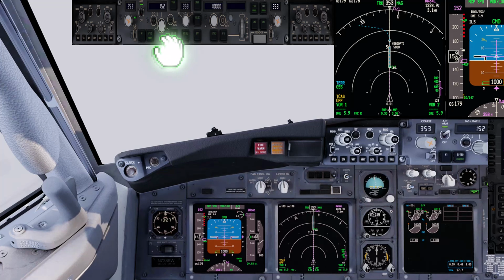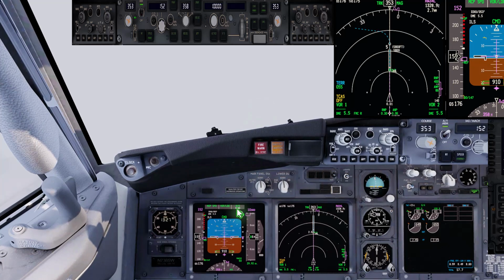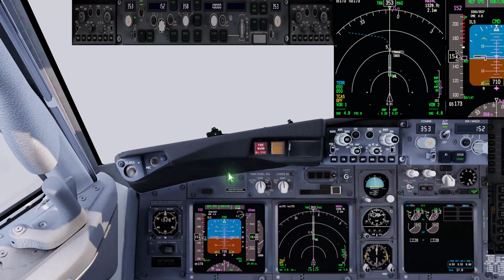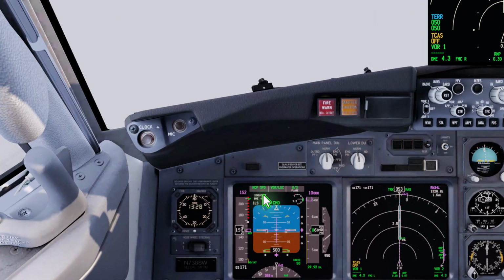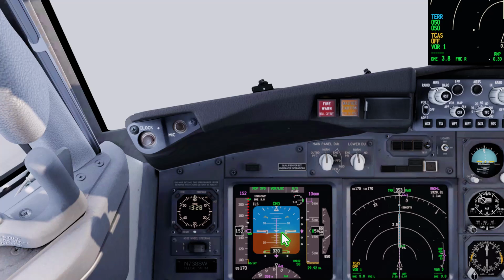Now what happened is we had that bit check. It went into command with both autopilots and I got a flare arm. That's important to have this flare arm for the autopilot landing. And I'm going to be freezing this at certain points here as we continue on this approach. Here's where it's going to start to get busy with scans that involve my FMA with a flare, with the auto throttles, and we're going to be looking at runway symbol come up. We're going to eventually lose the roll cue, pitch cue. We'll talk about some of those things when we freeze things here.